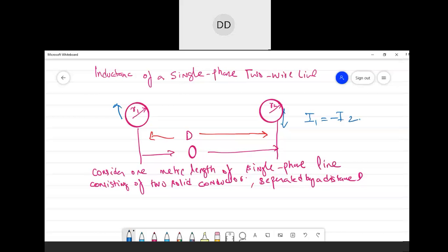The most important factor over here is that we are interested in calculating the total inductance. The inductance of conductor 1 is due to the internal flux and the flux up to d. The flux beyond d links a net current of 0. It does not link any current as such and does not contribute to the net magnetic flux linkages in the circuit.